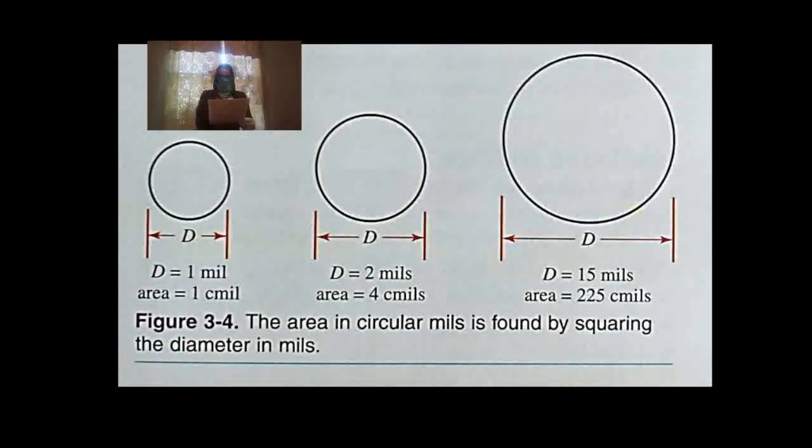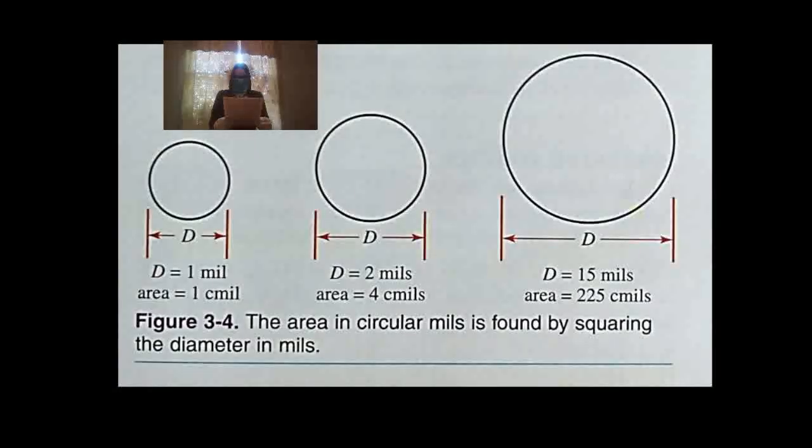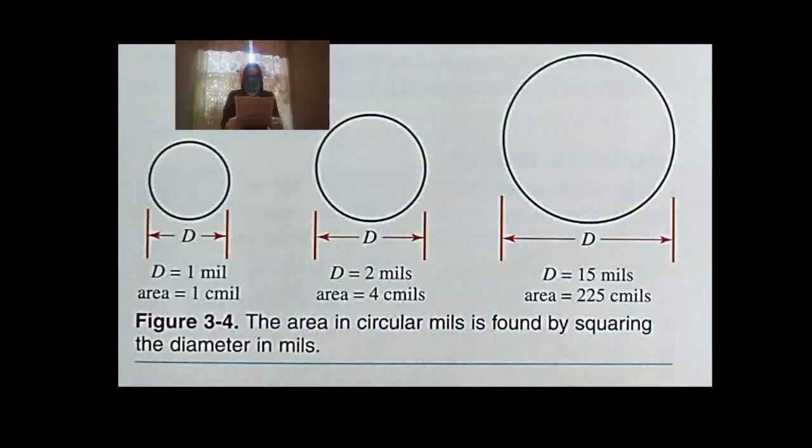The final system of sizing is the circular mil system. The circular mil system is based on a diameter of the conductor measured in mils, or 1/1000 of an inch. Typical conductors larger than 4/0 are from 250 kilo CMILs, or KCMs, to 2000 KCMs. KCM represents 1000 circular mils, so a 250 KCM represents 250,000 circular mils. Figure 3-3 contains all the wire sizes you would normally encounter.